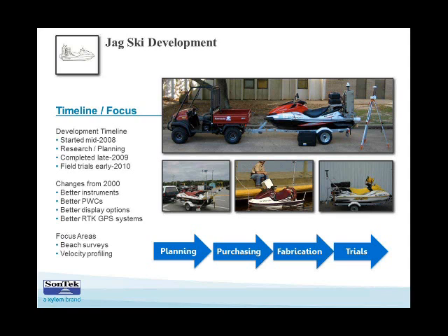So that takes a lot of the guesswork out of it, and on the RTK side it can provide better heave compensation if you want to compensate for that after the fact, which sometimes we have to do for the beach profile surveys if it's a particularly lumpy day on the water.